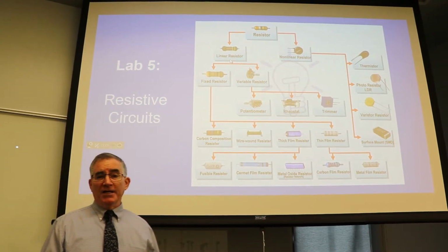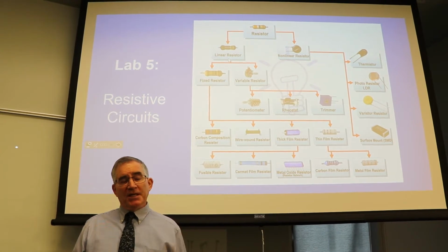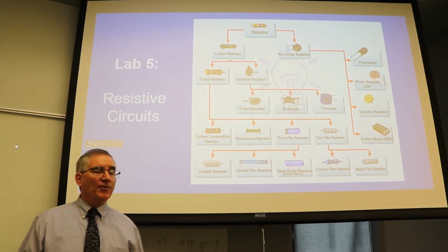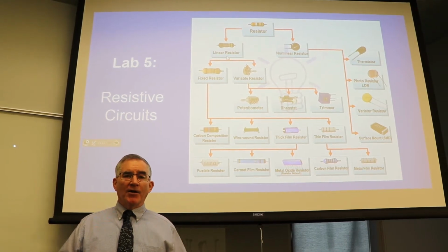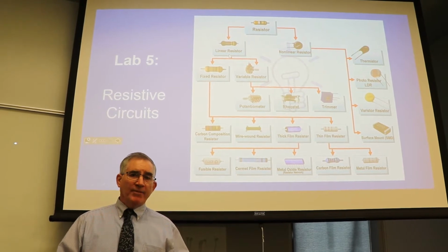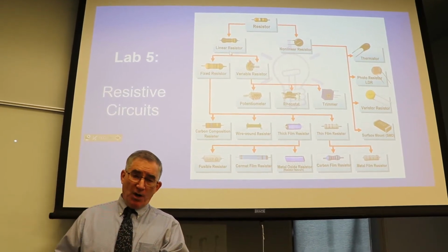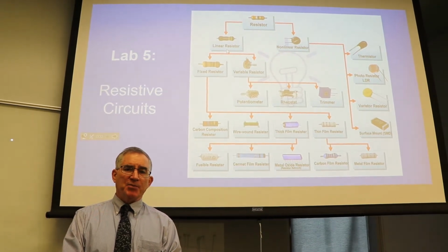It turns out that when you heat up a resistor, generally its resistance goes up. So you can keep that in mind when you're thinking about a little error in the experiment. We are using an experiment where our resistors are so big and our voltages are so small that we're really not going to see any big change in temperature.